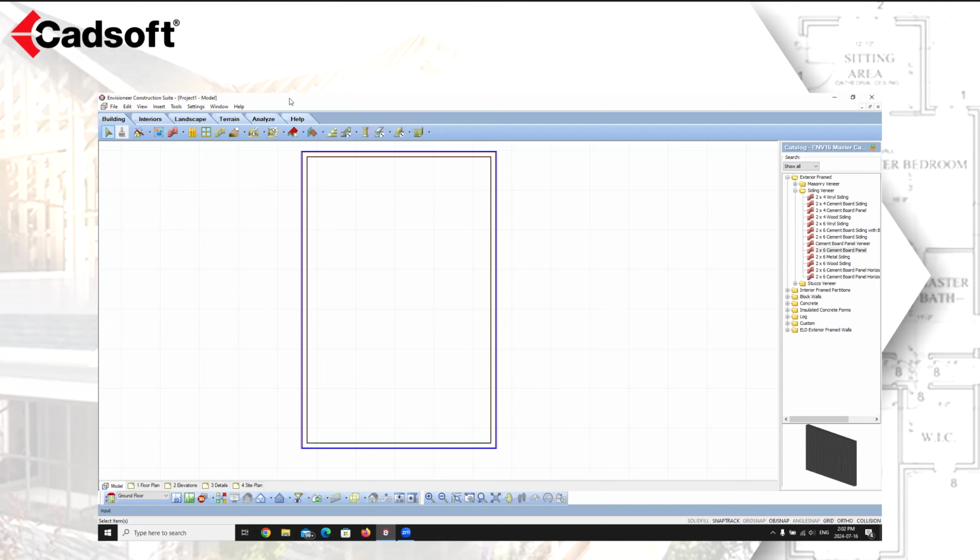So first, let's talk about roof rafter framing. Roofs have a framing configuration assigned to them that you see when you display your framing. Framing can be displayed using the display framing tool and is included in the project estimate. Settings in the framing configuration let you specify whether or not you want each component in the roof frame to be displayed and quantified. You can assign a member type, a usage, and a phase to each member in the configuration.